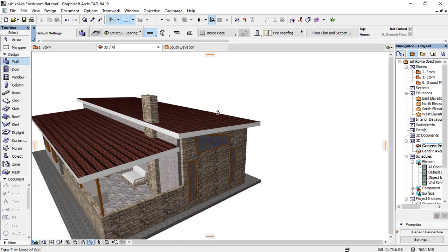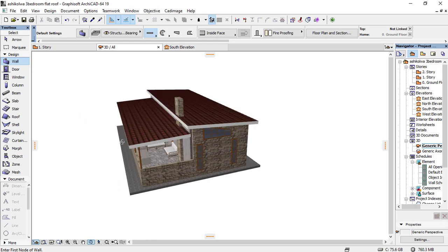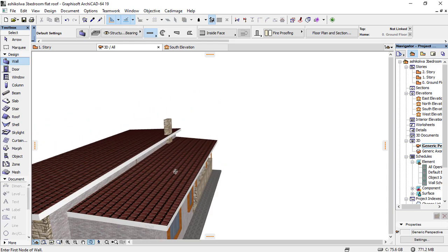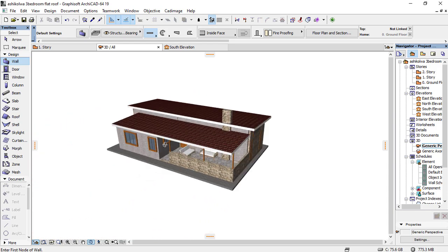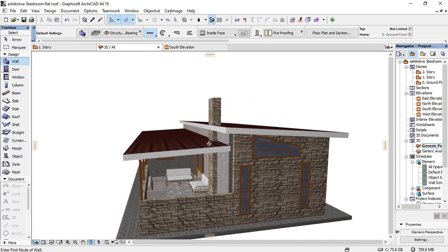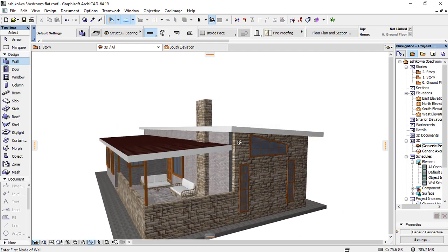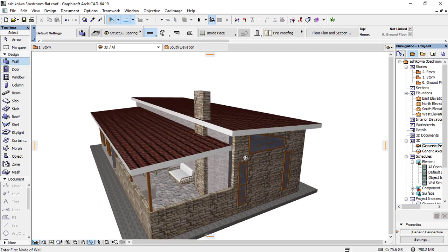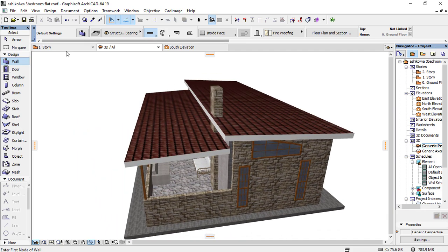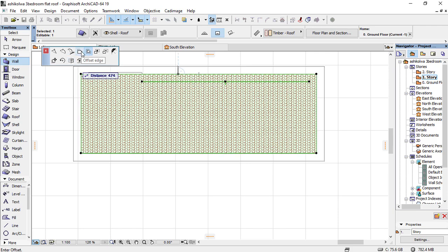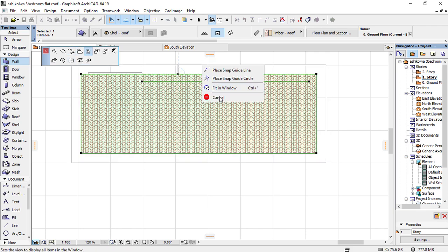with the wall. So this is how we design the flat roof, and the whole building is the flat roof, as you can see. And this is how you can design any type of flat roof or hip roof. So that's how you design, and you can increase the soffit size either by projecting, as you have seen. So basically for a soffit, you just select the roof, go to offset edge, and then you can increase the soffit.